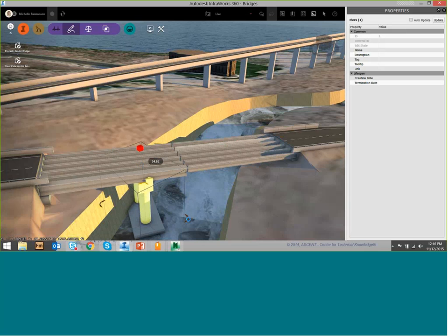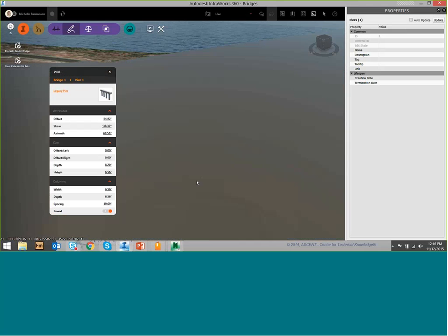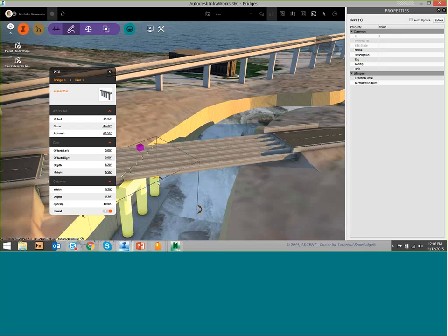And it has my rotate gizmos, so I can click on my rotate gizmo and change the angle of that, so that way I can let rafters go through without an issue. As I change that, notice that my girders are also changing. So this one lengthened, this one that I changed the style, it went ahead and shortened. So it's cutting across that pier for me.